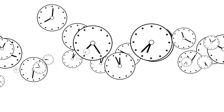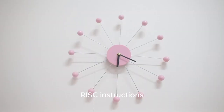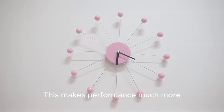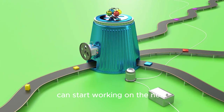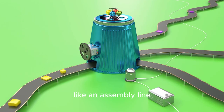Second, execution time. CISC instructions can take multiple clock cycles to complete because they're doing so much. RISC instructions aim for a single clock cycle. This makes performance much more predictable and easier to optimize through a technique called pipelining, where the processor can start working on the next instruction before the current one is completely finished, like an assembly line.